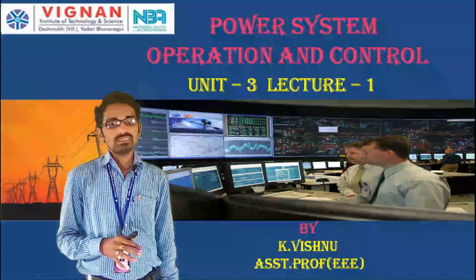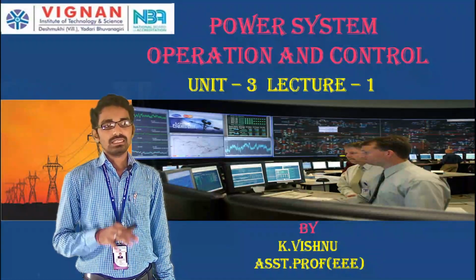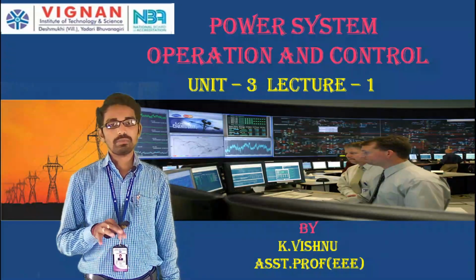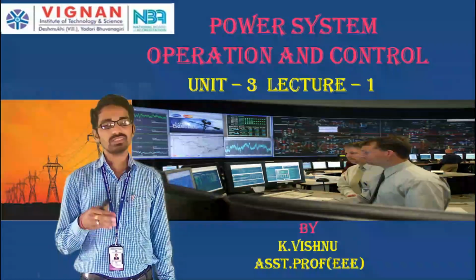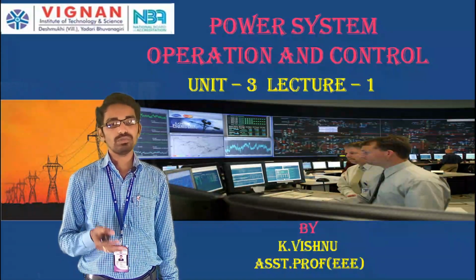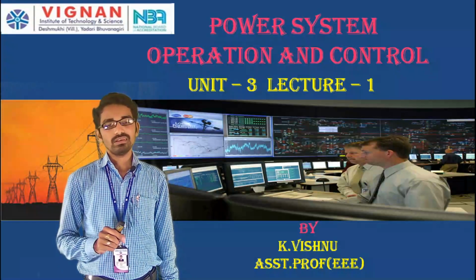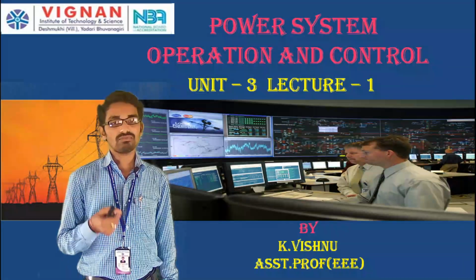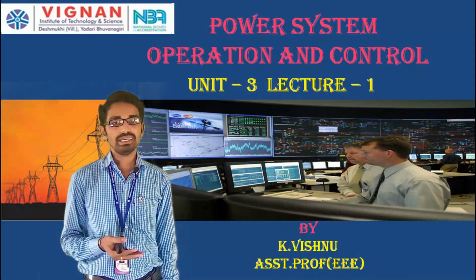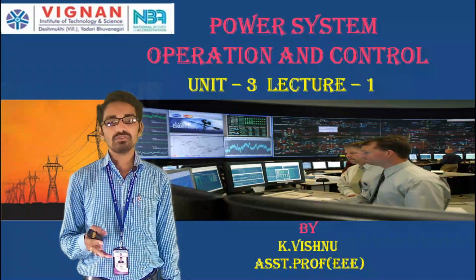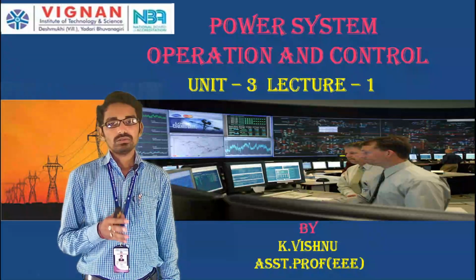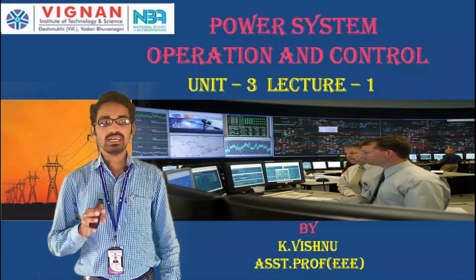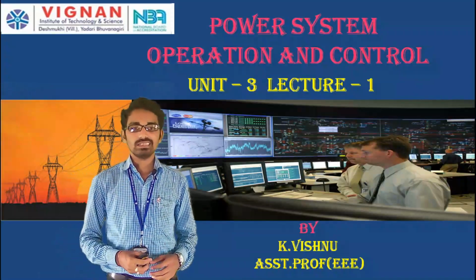With that we have completed the second unit, by having MVAR injection through switched capacitors onto the line to maintain a constant voltage profile. With the help of capacitors, by switching them on or off, we can maintain a constant voltage profile. Here the thyristors are used as switching devices. That we have completed in the second unit.